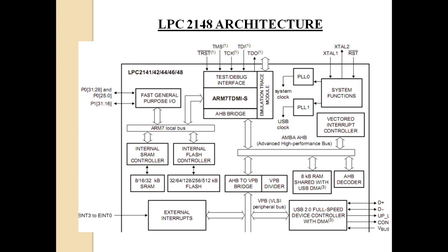Why is it not accurate? Because so many passive components are used for generating the clock. Because for making the astable multivibrator, you need to connect some resistors, some capacitors, etc. to the 555. So all these passive components will have their own tolerance. So the clock output will be slightly varied. It will not be accurate. So you cannot use that.